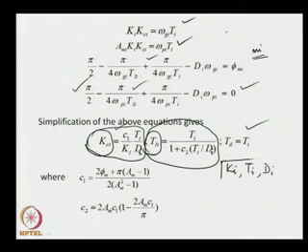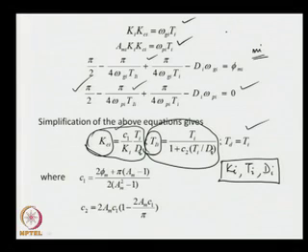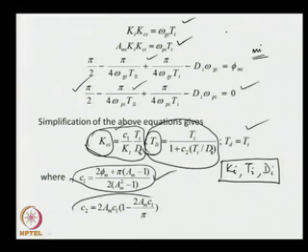So, these are nothing but the known parameters, since we know the transfer function models of individual loops now. Now, the C1 and C2 in the expressions are given. These are the two constants given in the form of C1 equal to 2 phi m plus pi times a m minus 1 upon 2 times a m square minus 1, and the second constant C2 is given as 2 a m C1 times 1 minus 2 a m C1 upon pi.